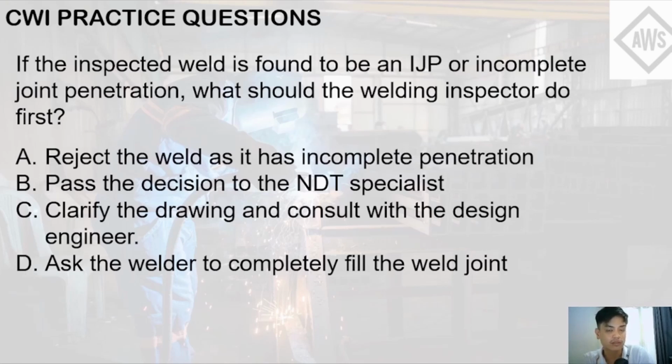So not quite. Basically the choice here is vague. You may not need to pass the decision to an NDT specialist here. It needs not to be specific to a non-destructive testing specialist. So it's just incomplete joint penetration. Basically, you can see the discontinuity or the defect just by looking at it. So the NDT specialist might not be the one that needs to be consulted immediately.